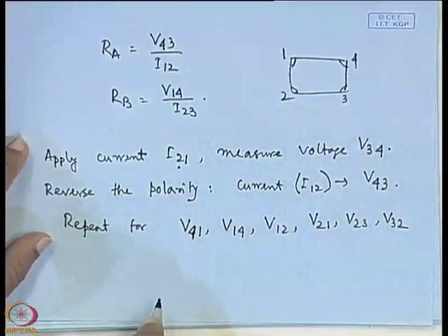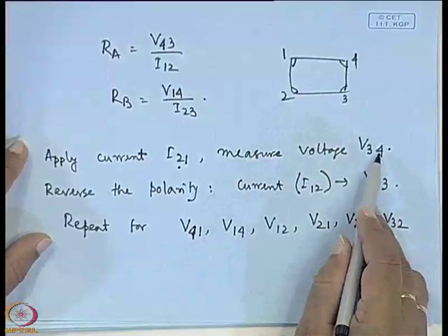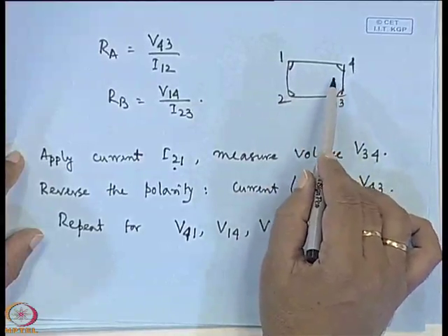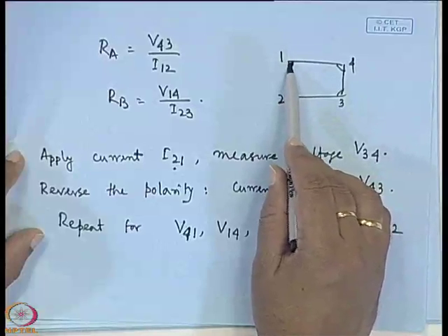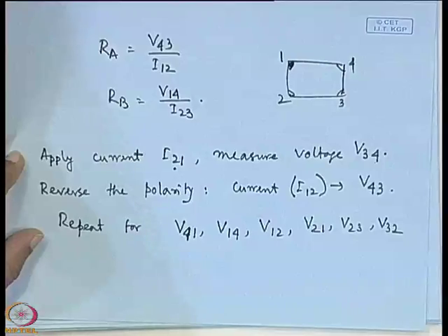Here also you find 8 voltages, because for 8 currents you will get 8 voltages. You send current, you record the voltage straight away, there is no ambiguity in it, and the configuration is in the counterclockwise direction. If you take this one as 1, then it is 2, 3 and 4, these are the small ohmic contacts. Small means the diameter is of the order of 1 millimeter.